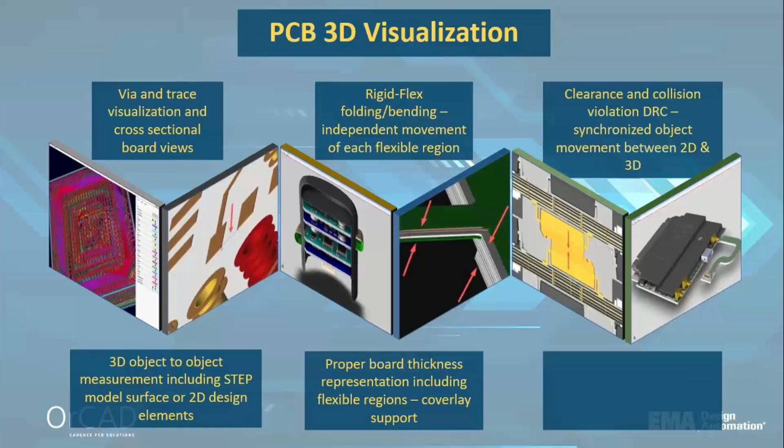You're actually going to be able to see what your design would look like if it was real. Even the cover lay is shown on the rigid flex material. And we also have full assembly views, so we can bring in STEP files like enclosures. We can add multi-boards onto it. Using STEP and IDX export allows us to do that.